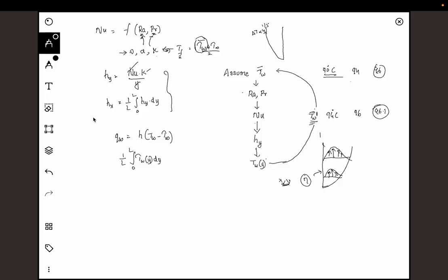And physically, what this assumption means is, if I know the velocity at y1 and I know what y2 is, I can compute the entire velocity profile at y2 just by knowing y1, y2, and this velocity profile. What that also means is the flow has reached a point where it doesn't depend on how it started out. We do not care what happens here. It doesn't matter to me what happens here. If I know the velocity here, I can compute it here. Similarly, if I want to calculate at a different point, I don't care what happens here. If I know this one, then I'll be able to do this. So this is something called memorylessness, where the flow actually forgets how it started, but eventually gets into this particular stage. This is an assumption where you do not have any obstructions.